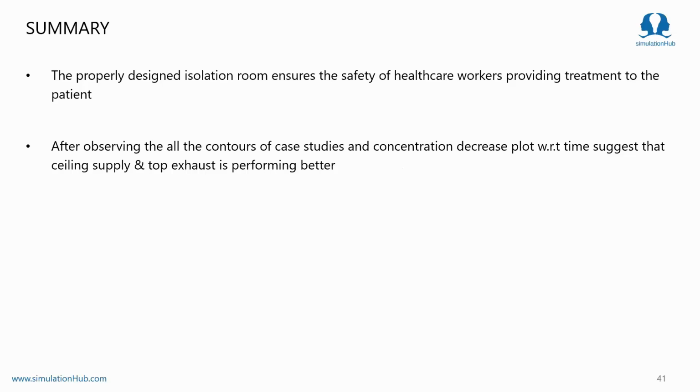And I would like to add here that these results are only applicable to the inputs we have considered. And one more thing is that CFD is highly dependent on the physical space, the presence of any objects, or the diffuser type itself. So every time you need to perform the CFD simulation to get the key insights. So in a way, an HVAC designer can use CFD to evaluate his design, perform the design cycle very fast, and make his design better.